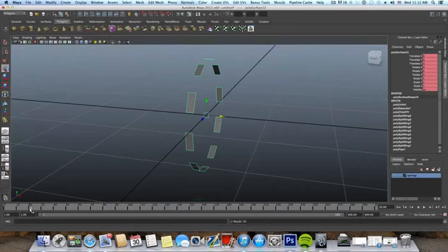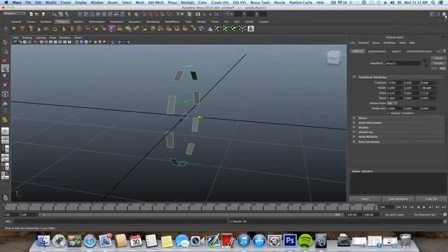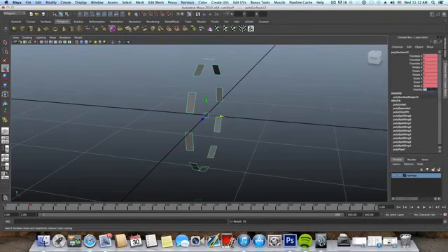You can see we have a red mark right now, and now I want to move this frame to frame number 0, and I want to record this again by pressing the S key, but this time I want to change the visibility value here on the channel box. This is the channel box again, and I want to change it to 0, which means off. So 0, and hit the bigger enter key, choose this, hit it, and the object will disappear.